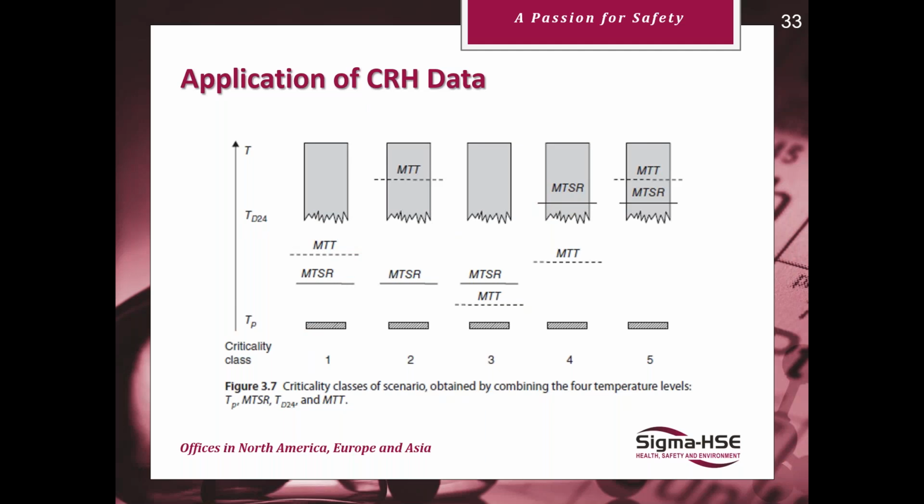Class 2 is similar. However, as you can see, the boiling of the solvents is equal or greater than the temperature of decomposition, which means in the case of inadvertent heating, we don't have access to that safety barrier of tempering the reaction. So for these two classes, if heat accumulation can be avoided, no special measure is required.